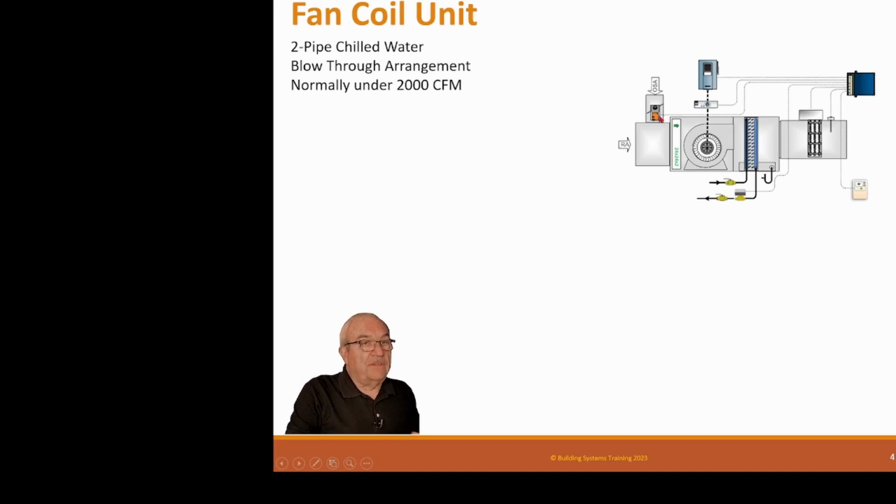And then it'll have this damper actuator. And the reason that's there is when this unit's off, this is to be closed. So we don't get outside air infiltration into the building when the unit's off. Then, of course, this one has a chilled water valve over here that's run by this controller. And then we have, in this one, heat. We have an electric strip heater here. And we also have a discharge temperature sensor to be able to monitor the supply air temperature. And then we have a room temperature sensor.